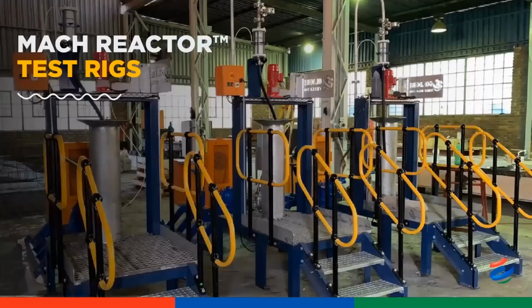There are semi-pilot Mach reactor test rigs available at Mintech and at ALS in Perth, and soon also at SGS in South Africa, where test work with a 2-scale model of a Mach reactor may be performed. Initial scouting work that tests a base case together with a couple of different Mach passes would require circa 50 liters of pulp and would cost in the region of $10,000 to $15,000 US. Not a lot of money to ascertain whether you are likely to see a benefit or not, and a no-brainer in the light of the incremental monthly profit that could be attained.